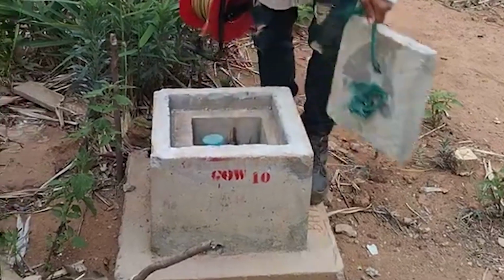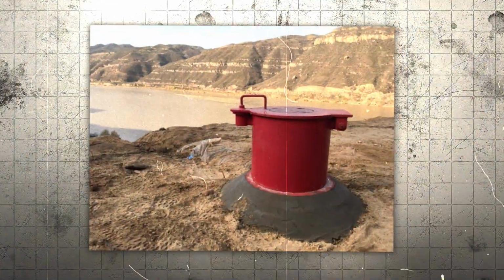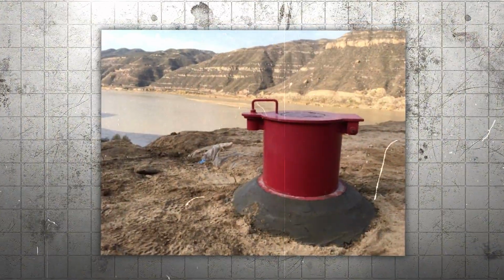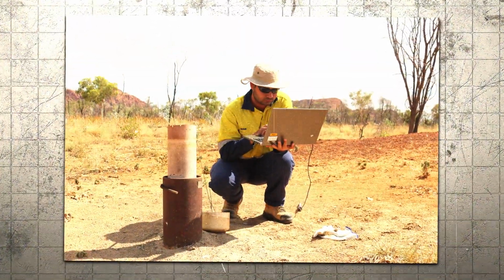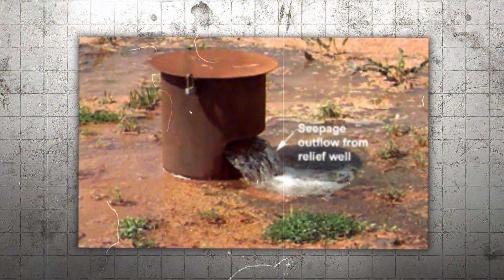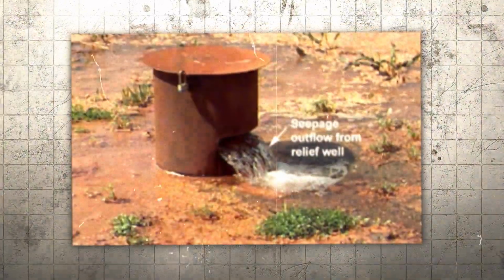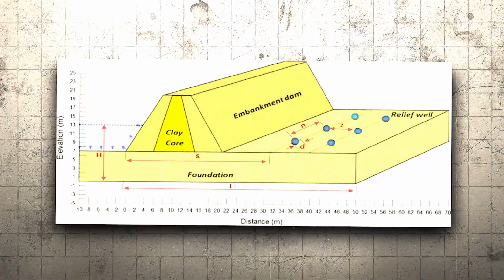Another type of tool that can be used is something called an observation well. These are small wells that are drilled into the ground around a dam. They allow engineers to measure the water level down below and see how it changes over time. If the water level in these wells rises too quickly, it could be a sign that seepage is increasing. Then, an investigation can be done to look into why this is happening.